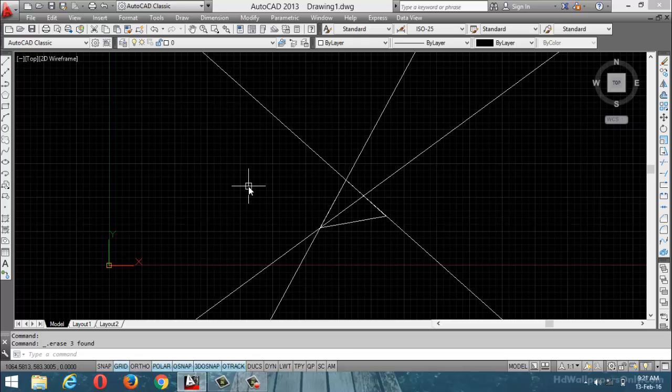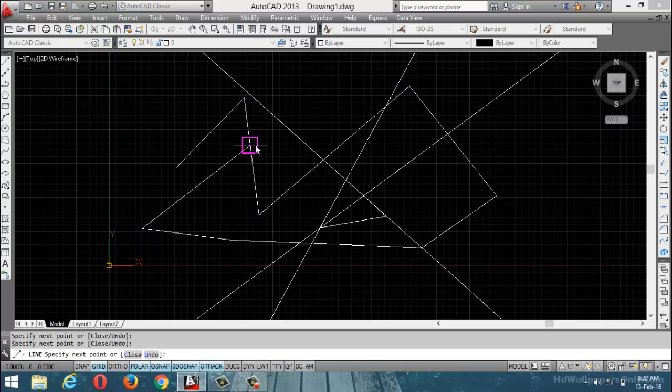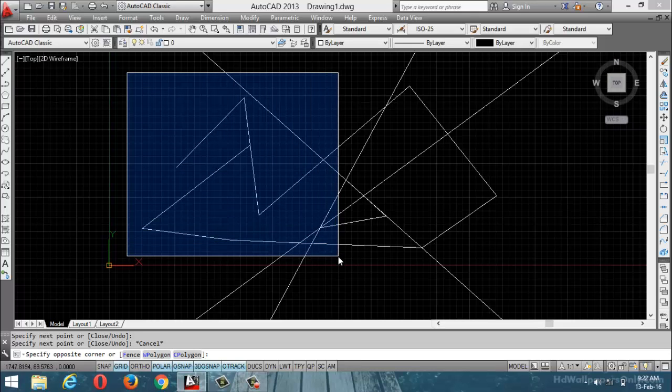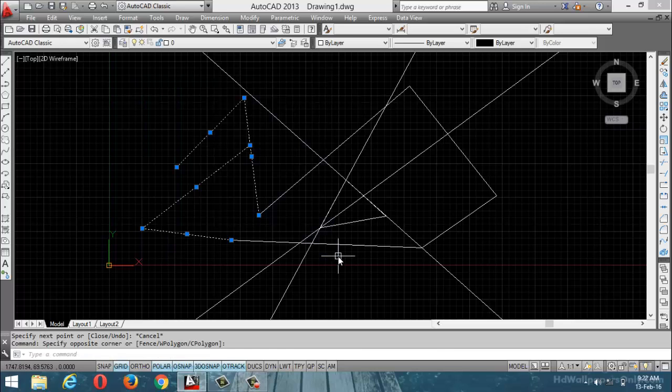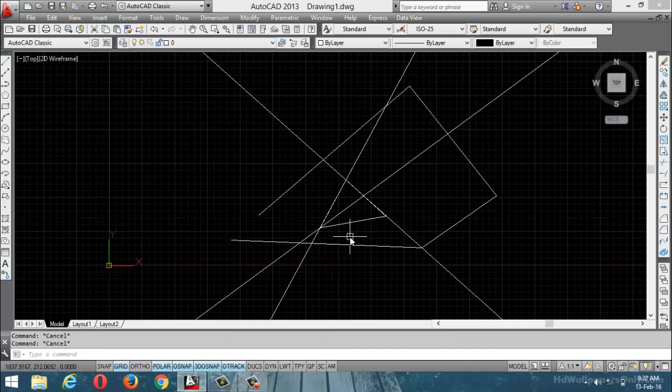Okay, then next my requirement is, now see here, again I am going to design some designs here. Now my requirement is just to delete from this line to this line. For that purpose, I use window selection, delete. Okay, then next one, how to delete the entire thing? Control A is select all.